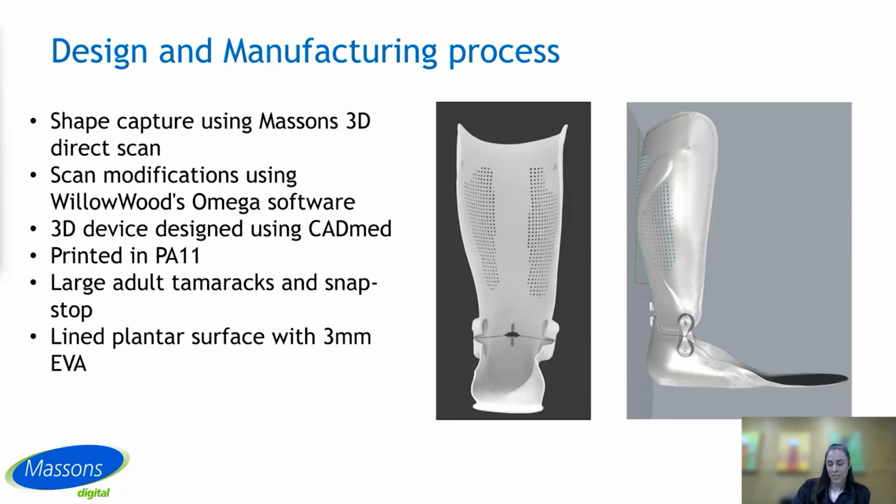In our first attempt at designing this AFO, we printed the AFO on the left of screen. Once printed and vapor smooth, the proximal shell had far too much torsional flexibility, which we anticipated would lead to premature breakdown around the joints if worn daily by the client. The second and final